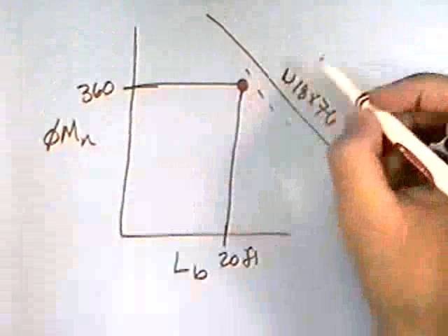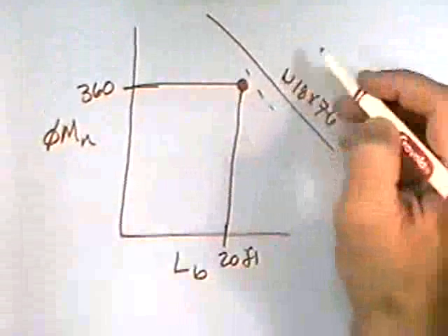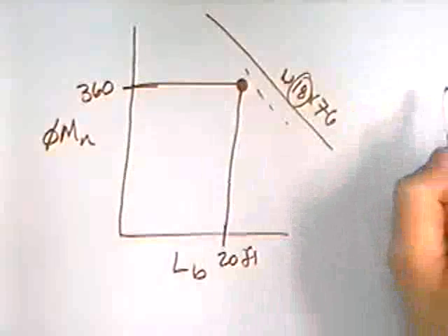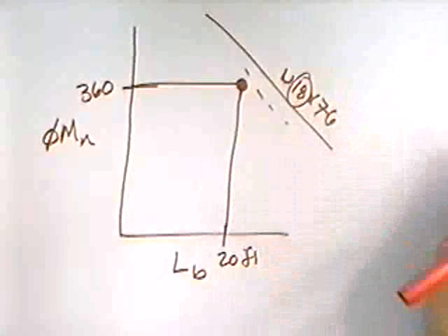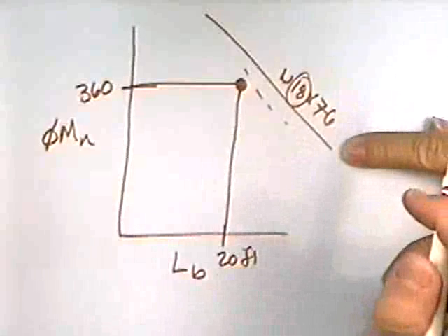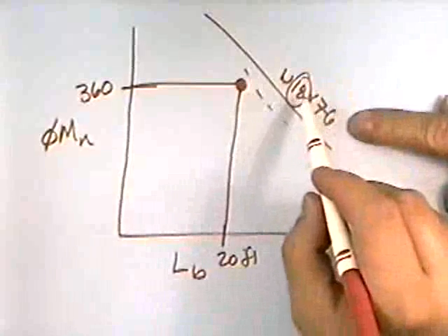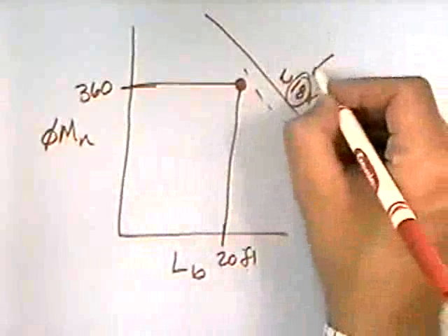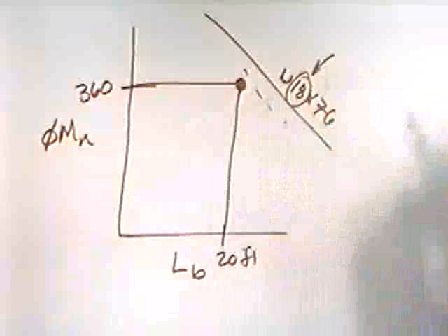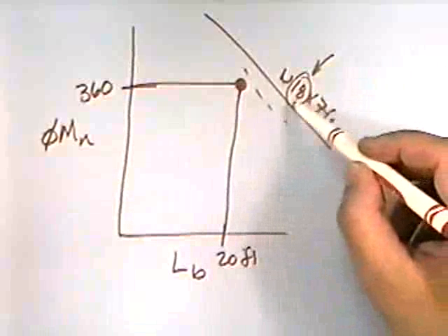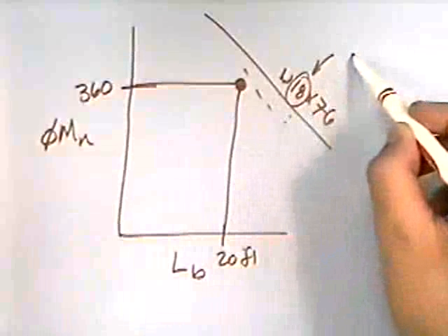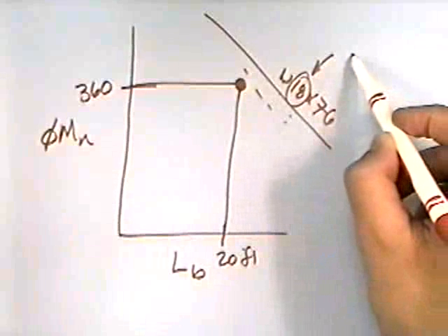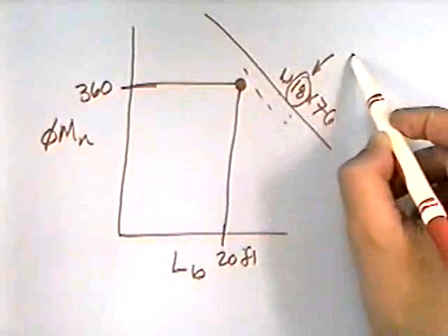No, actually, that's wrong, because it's the first. If you're asked for a given depth of beam, that's what it is. In other words, you may have had to skip a couple of solid lines to get to the lightest 18. Because if you're told to pick a certain depth, and the depth is given by the first number in the designation, you can't get a dash line, go up and get a solid line that's lighter in the same depth cross-section. Hope that didn't confuse you more than it helped you.